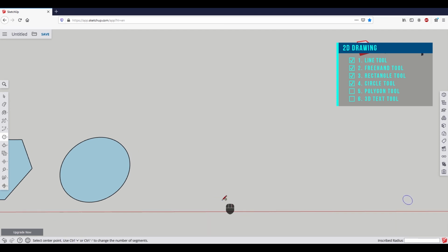At this point, I would like to give you some additional information, especially about the polygon tool. We have already learned that we can adjust the number of sides when reselecting a tool from the toolbar. This will apply for the circle and the polygon tool. So if we now reselect the polygon tool, we have the previously set 100 sides, but we can directly enter a new number to change the amount another time. For example, we can type in 3 and confirm by pressing the Enter key. And now we can use the polygon tool to draw a triangle.